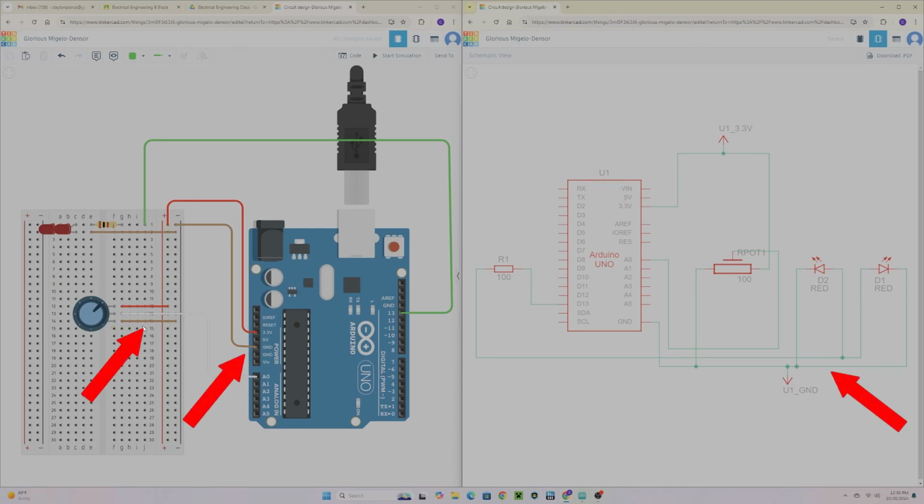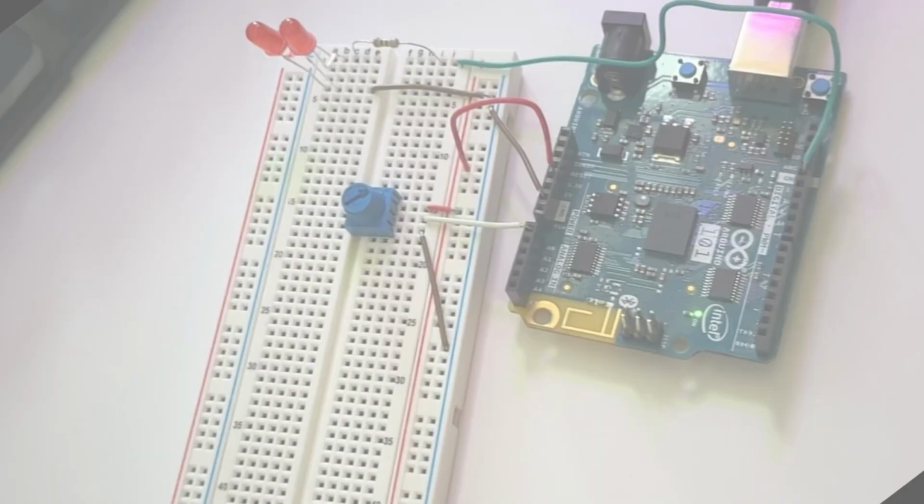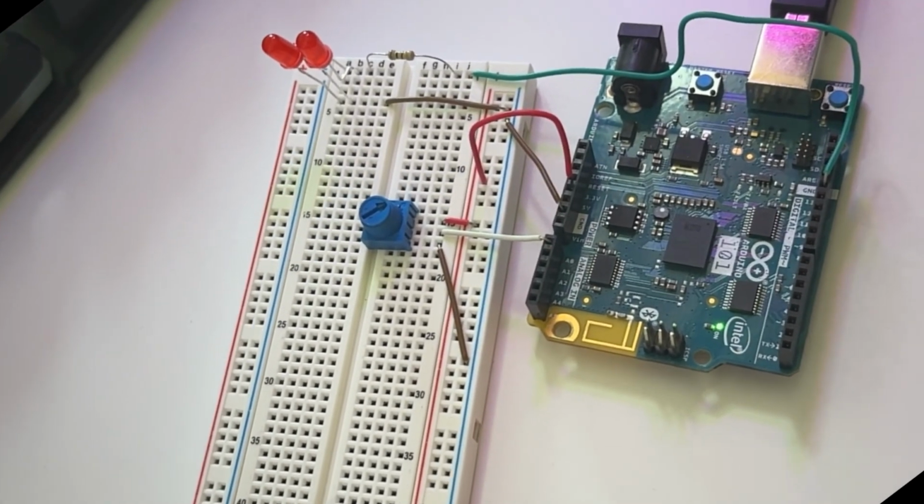The ground wire is right here below it, and the potentiometer has a value between 0 and 1020, which analog pin 0 here reads. Once analog pin 0 reads this, the code in the board, depending on what the value is, either gives off SOS in Morse code or my name in Morse code, and powers pin 13 accordingly to make the LEDs blink.